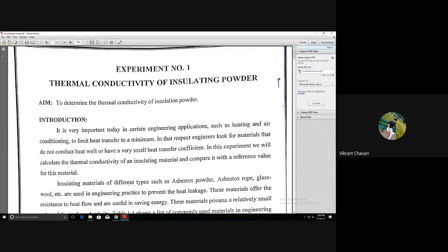If you replace the brick structure with steel walls, in the summer season most of the heat will enter your house, and in the winter season the cold present outside the house will also enter your house. So bricks are good insulators. Brick is one of the insulating materials because its thermal conductivity is very low.